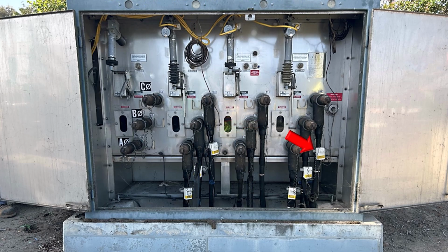The little white boxes attached to the cables on way 2 and 4 are part of a fault indicator system. The boxes are current sensors that monitor the electrical current in each cable. If a fault occurs, these sensors detect the sudden increase in current and trigger a little red flag to pop up in the glass window at the top of the switch cabinet. This helps line workers detect the location of a fault without actually needing to open the cabinet. Once the fault is cleared, the indicator flag will be reset for next time.